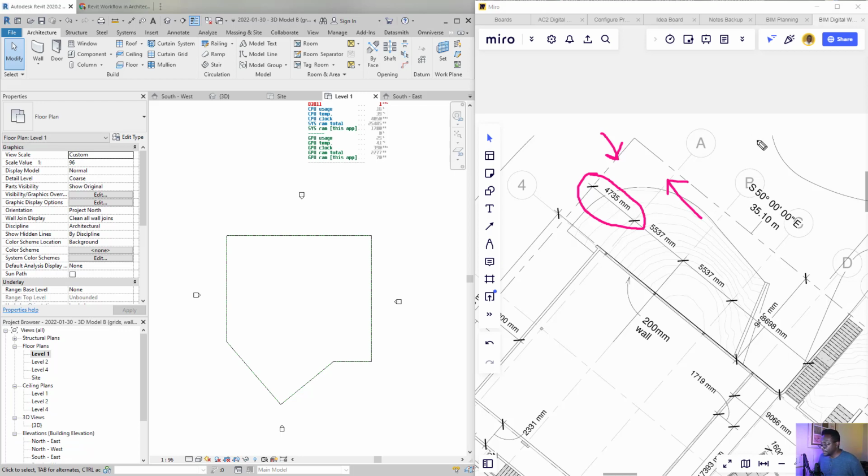Remember, we established our boundary lines from the coordinates, which would have been from the surveyor. So that will ensure that we are 100% accurate. Now, what we want to do is establish our building location based on the boundary line. So this drawing here begins to set that up.